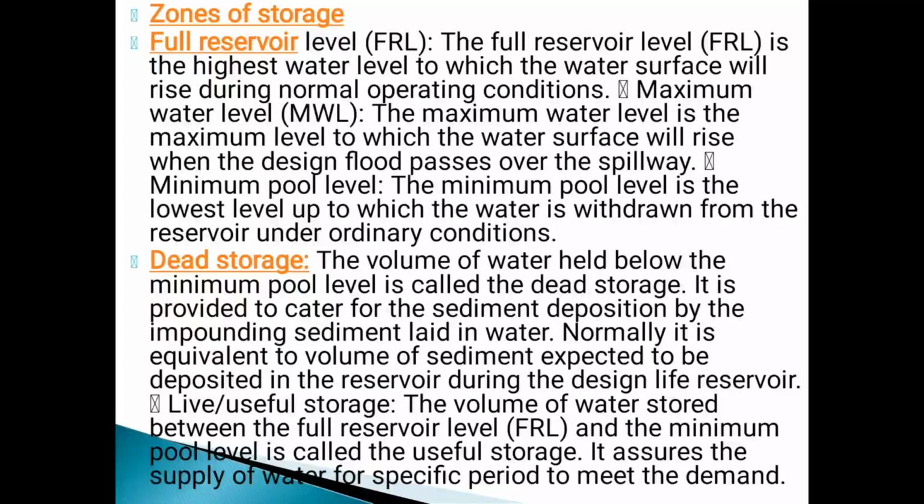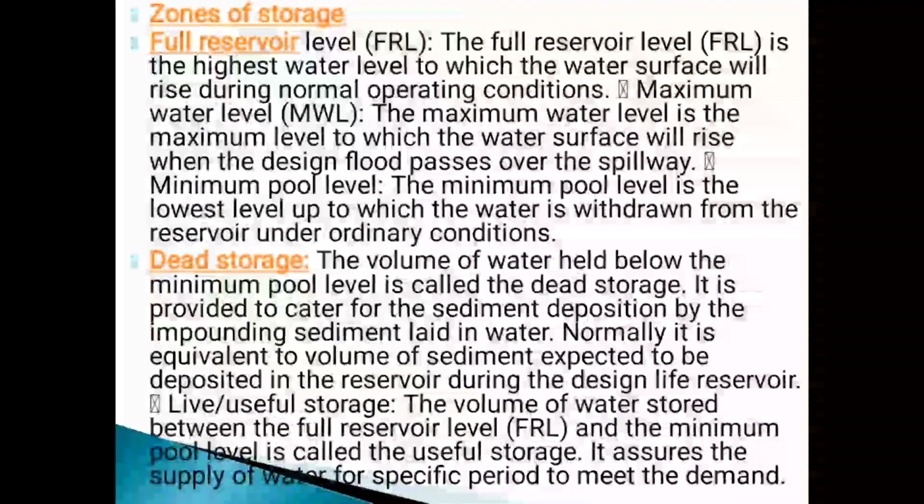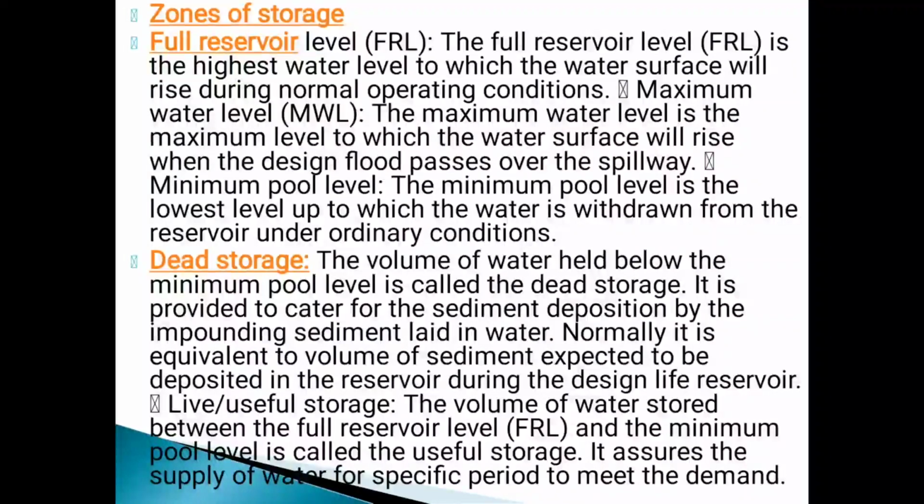Next one, dead storage. The volume of water held below the minimum pool level is called dead storage. It is for impounding sediment laid in water. Normally it is equivalent to the volume of sediment expected to be deposited in the reservoir during the design life of the reservoir. Next one, live or useful storage. The volume of water stored between the full reservoir level and the minimum pool level is called useful storage. It assumes the supply of water for a specific period to meet its demand.